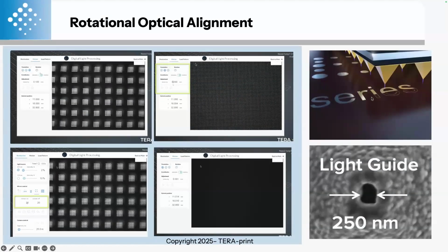After you establish the physical alignment between the array and the substrate, we want to make sure all 30,000 probes are in contact with the substrate. First, we use the bigger window of light, and you see every single projection might look different when you first start the projection. We want to use the rotation setup to rotate all of the projections until they look identical. Next, I'm changing the projection of light into something smaller.